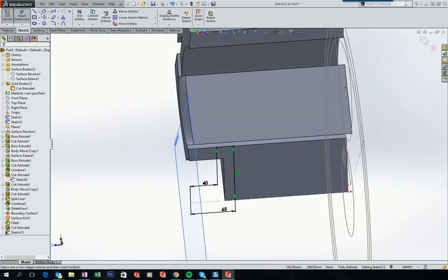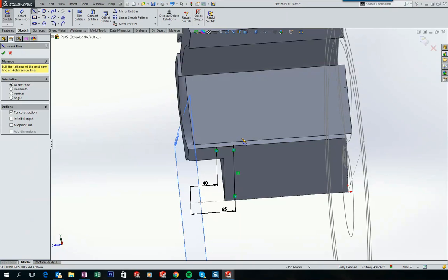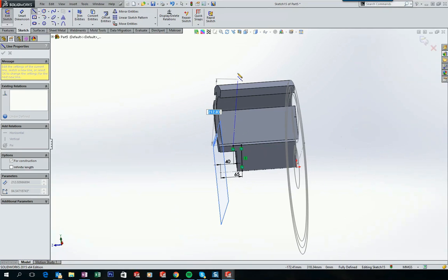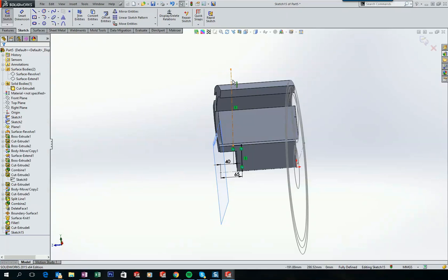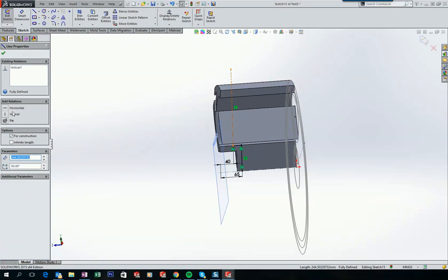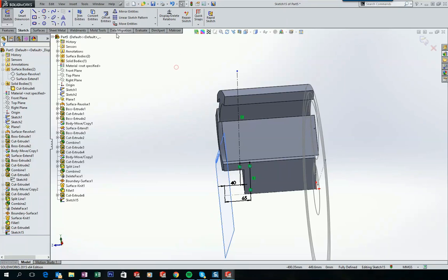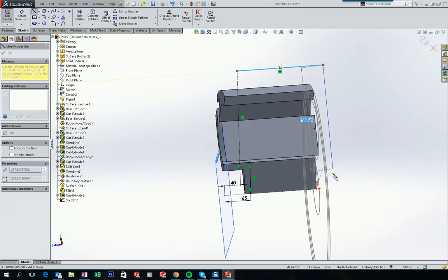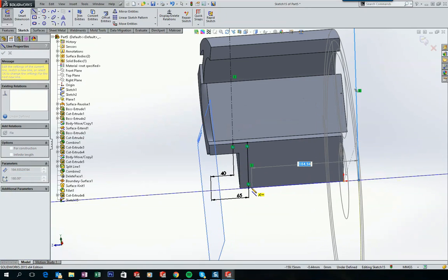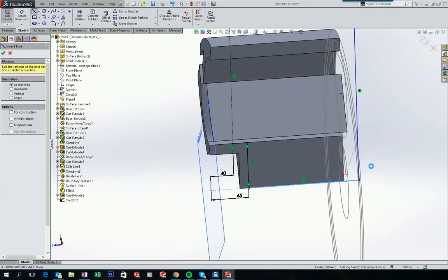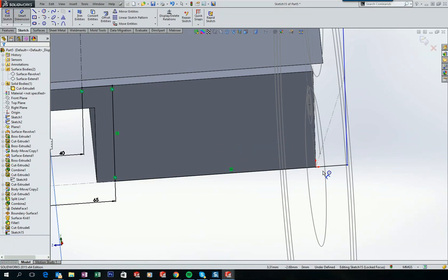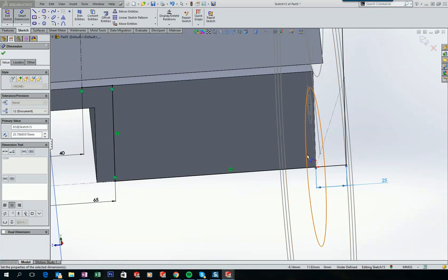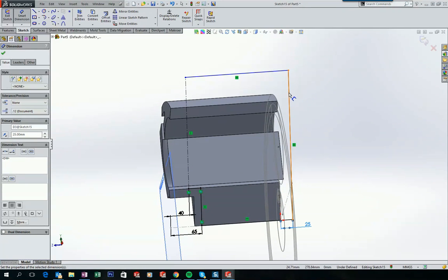Now choose your center line tool and sketch a vertical line here. And make sure this is given a vertical dimension. Choose your line tool again and sketch a line here, one more here down to the origin. Finish in this endpoint. With the Smart Dimension tool, make a dimension between the origin and this point of 25. Give this line a dimension of 300.